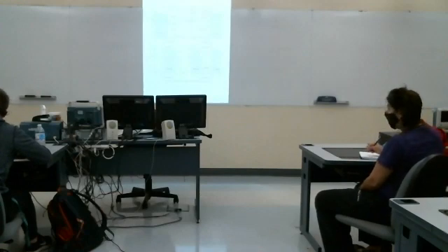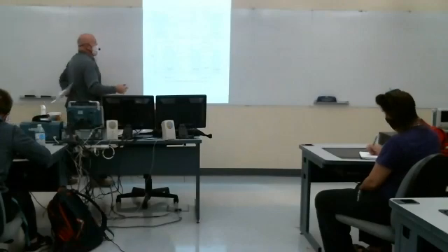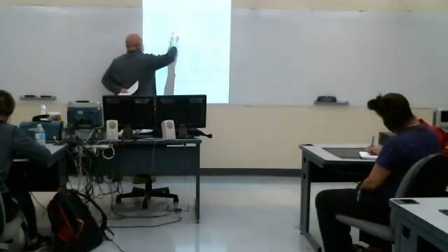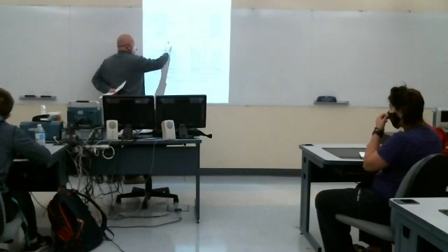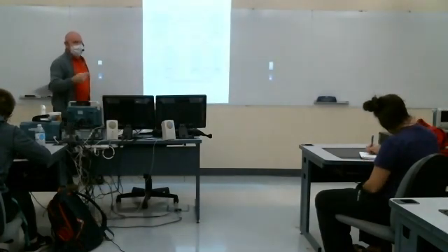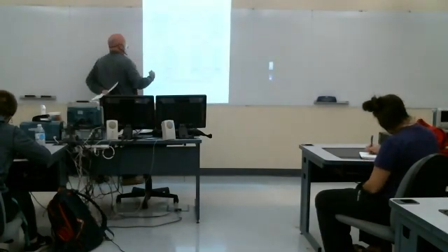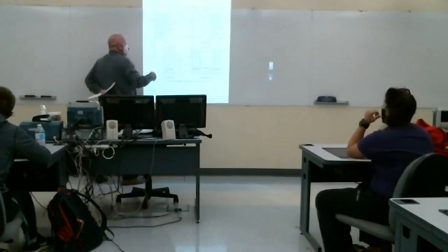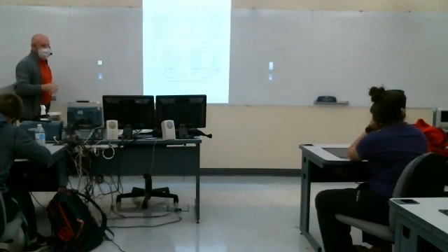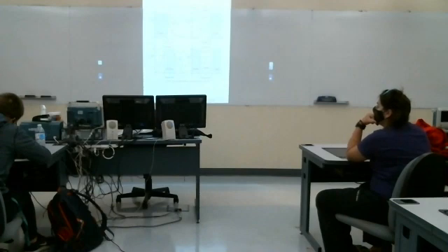What's plotted there are the magnitude responses of 4 different filters. So again, what may be given is a graph something like this. And from the graph, you pick off the omega C, the corner frequency. And then you can actually use the slope here to determine the order of the filter as well, to lead you in the direction of the filter design.